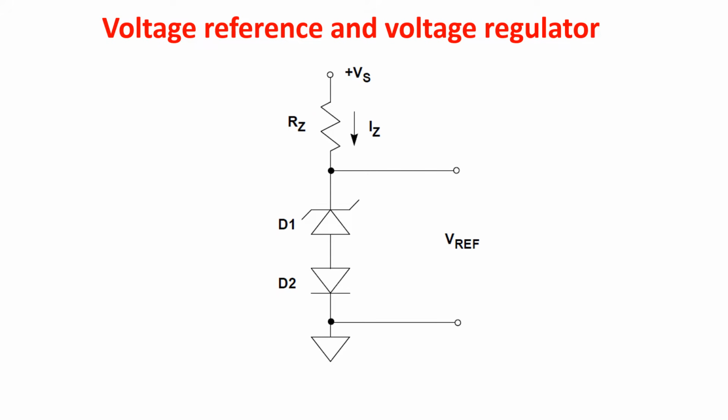The Zener diode has a fixed reverse avalanche breakdown voltage, and when this is set between 5V and 8V, its positive thermal coefficient compensates the negative thermal coefficient of the diode D2. With proper bias current in the diodes, we can reach a thermal coefficient of 100 parts per million per degree Kelvin. Since the best thermal compensation is at an odd voltage level, the accuracy is limited. The load is also limited since the bias current must be carefully controlled.